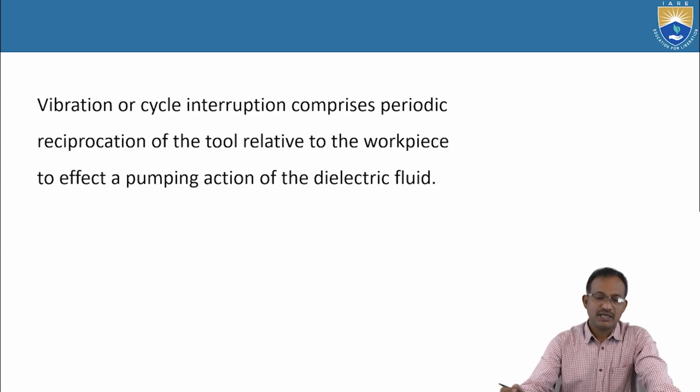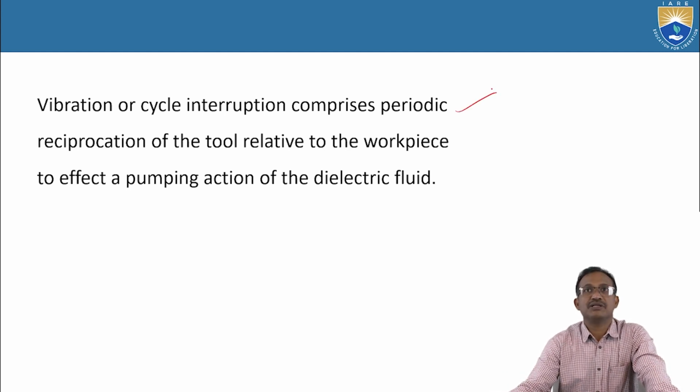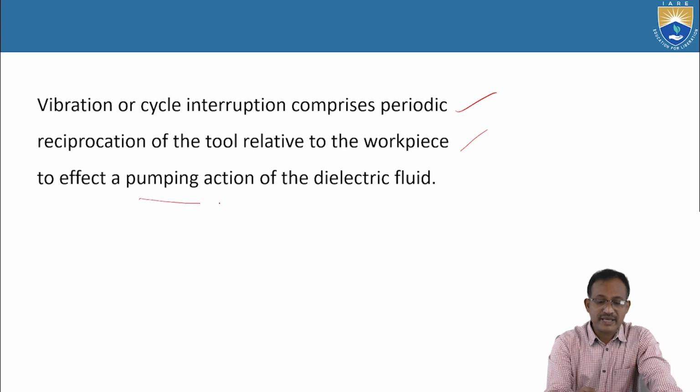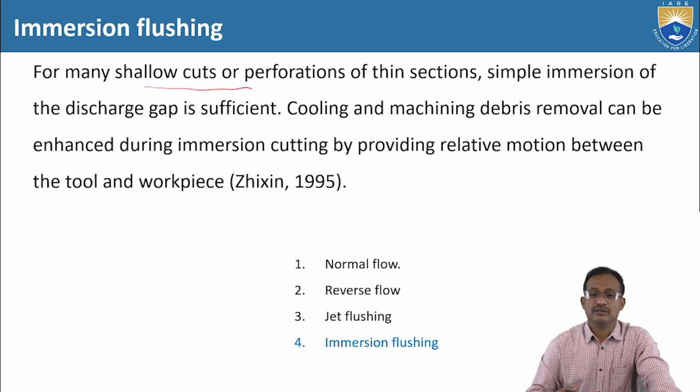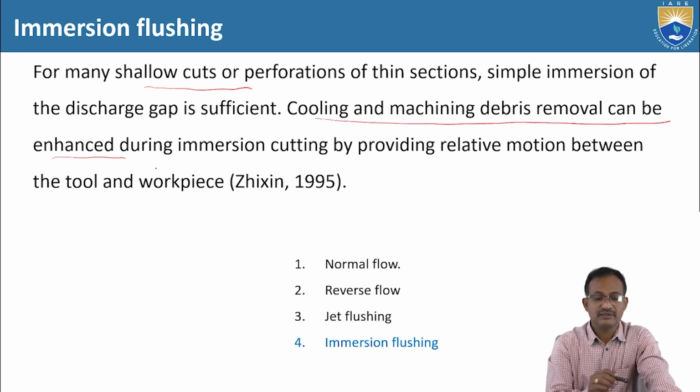In addition to that, vibration or cyclic interruption comprises periodic reciprocation of the tool relative to the workpiece to affect a pumping action of the dielectric fluid. So in addition to that, cooling and machining debris removal can be enhanced.